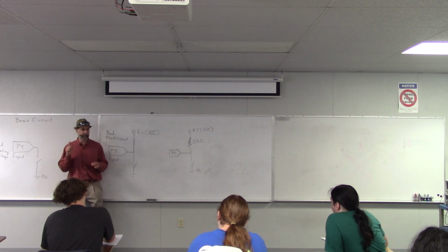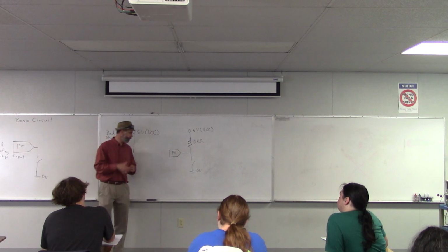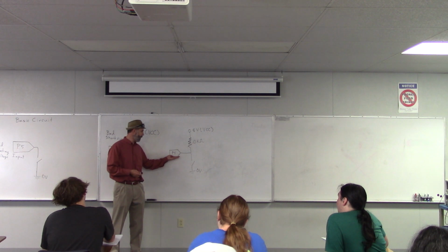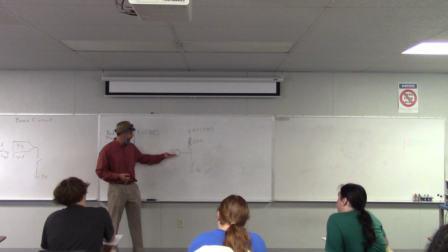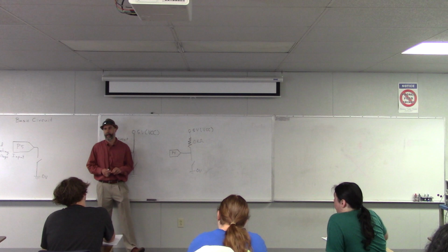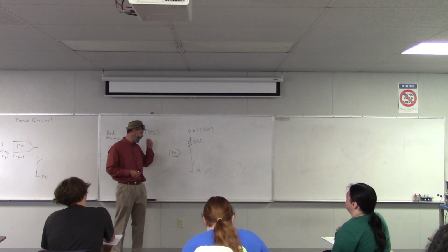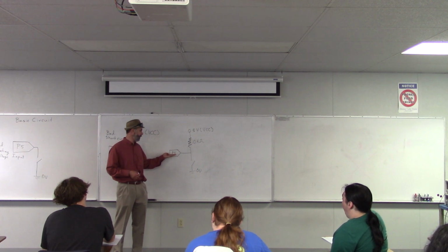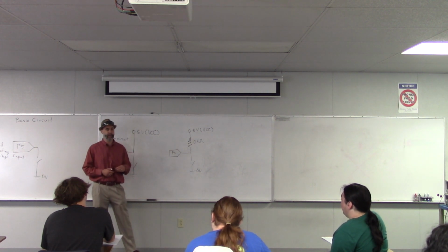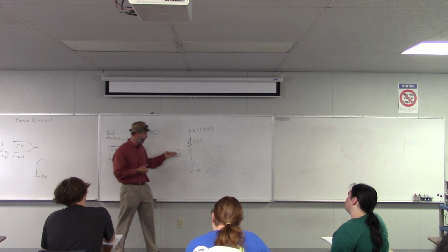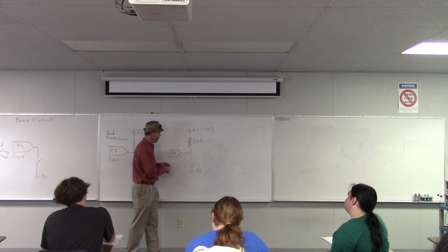But there's still one minor little problem with this circuit, and that is that somebody might write a program and accidentally make this pin an output instead of an input. Say they accidentally made this pin an output and made it put out 5 volts. Now the switch gets closed.